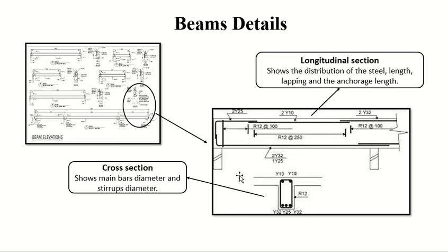So we cannot say it's the number of stirrups, because where are the stirrups? One here, one after 1 meter, one at the end. So if you do 2 divided by spacing, you are missing the end. This will give you how many openings you have. When you just divide by the spacing, it gives you how many openings you have, not the number which you want.